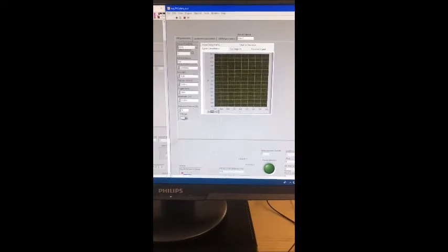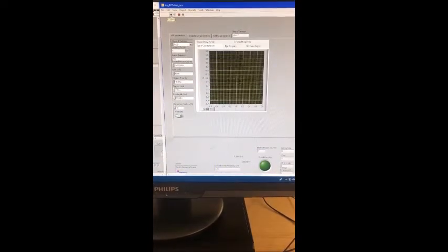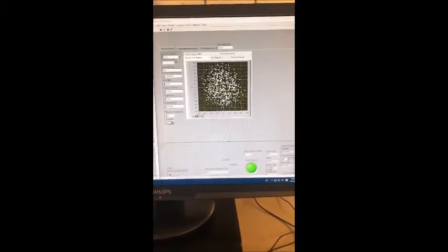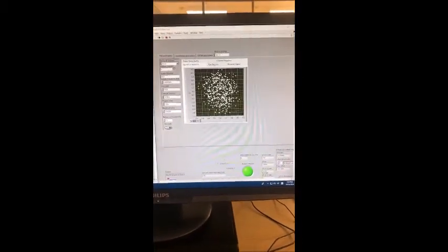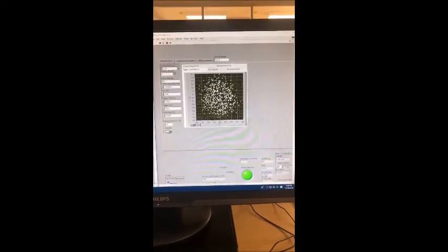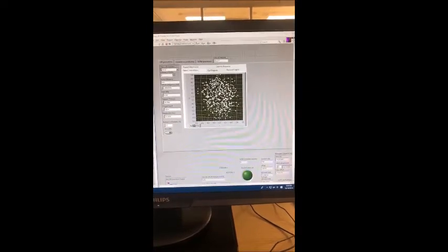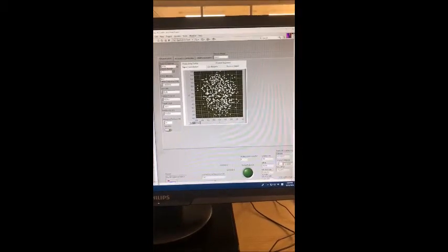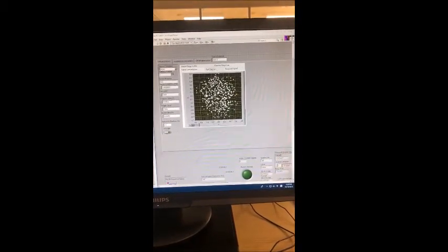Our first simulation is to test the modulation result when the probes are touching each other. Always remember to run the receiver first, as the receiver has to be ready before the transmitter transmits the data. As you can see, the constellation points are not located at the desired location, as the signal sent from the transmitter has been got reflected by hardware to hardware, and then only received by the receiver, which has caused delay.